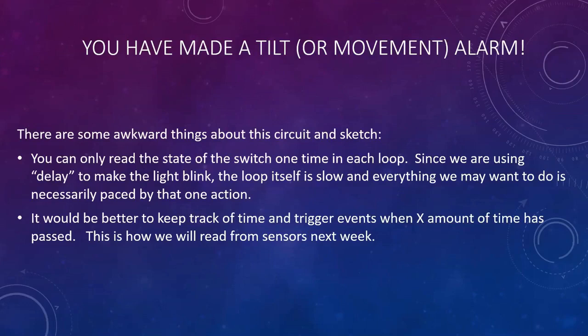It would be better if you could just somehow keep track of time. And once a certain amount of time has passed, tell pin 13, okay, beep. And in the meantime, every millisecond, you could be checking the state of some other input pins or reading from some other analog inputs even. And we'll get into how to do that next week when we cover sensors.